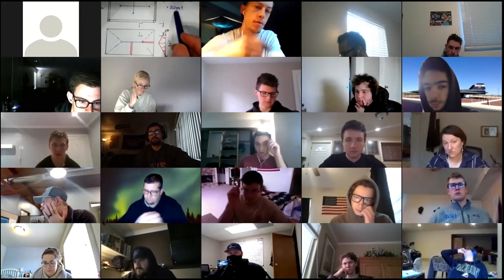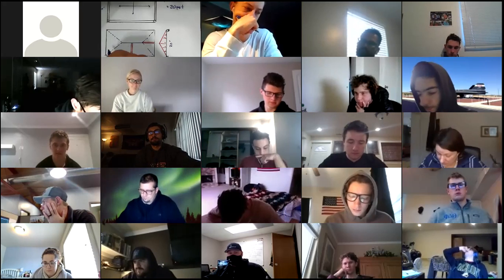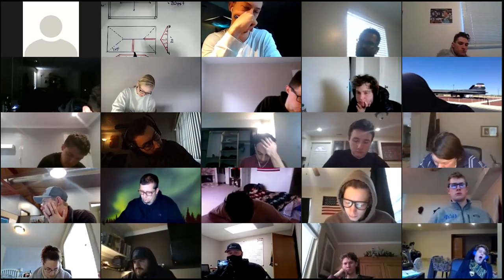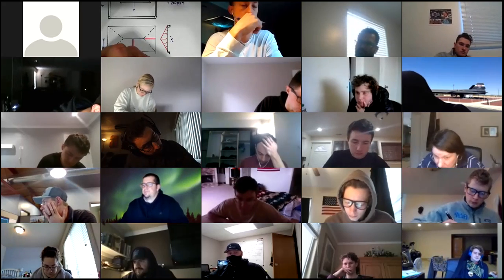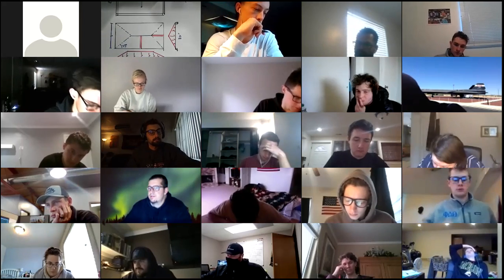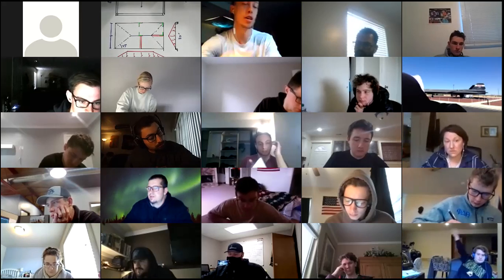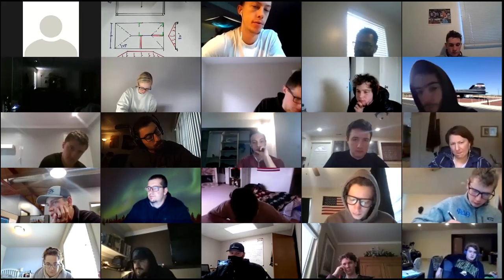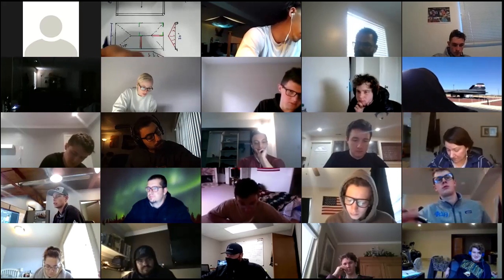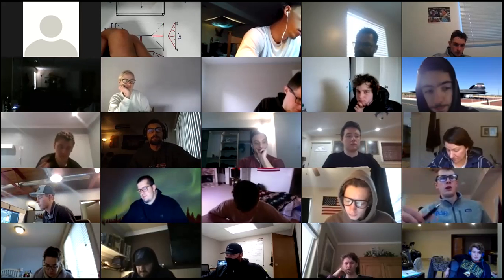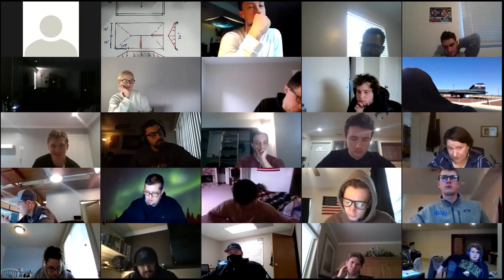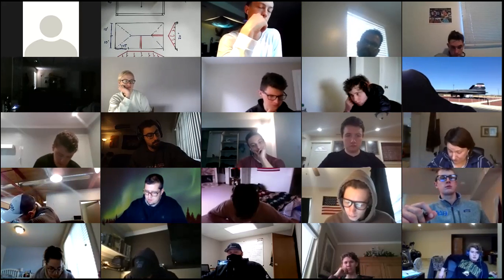All right, so there's your value. Now let's get some dimensions here. If this is 45 degrees, then it turns out to be pretty easy, right? Because that distance here and that distance there have to be exactly how much? 10 feet. Okay. So you use the little triangle to figure that out. So what does that mean about the distance from here to here? What does that have to be?